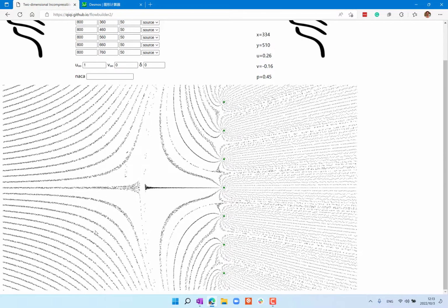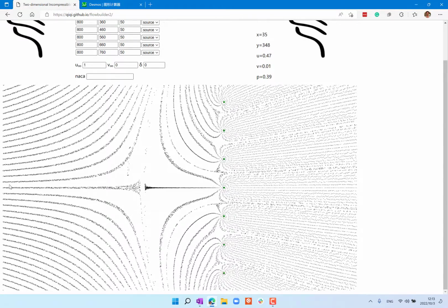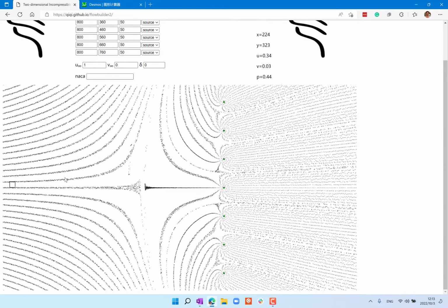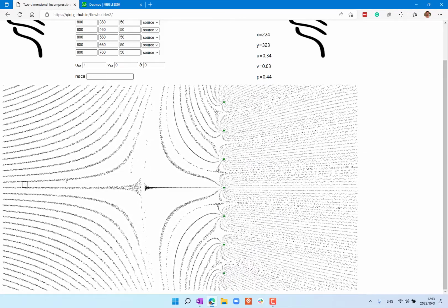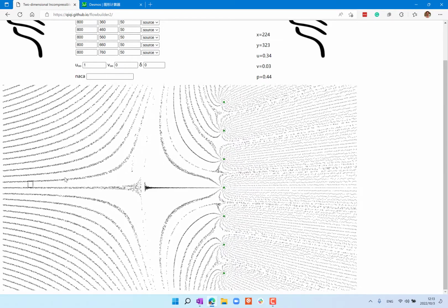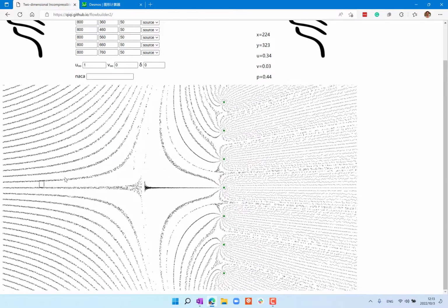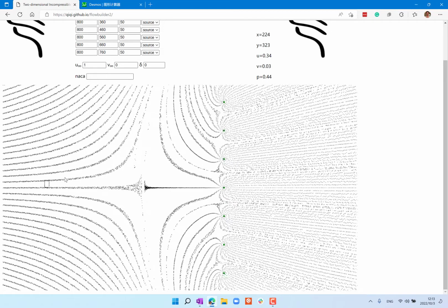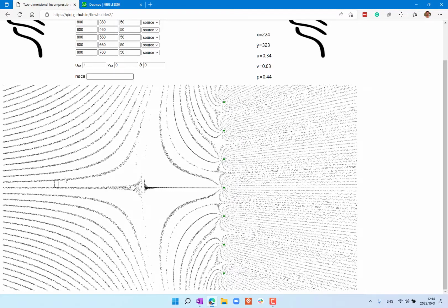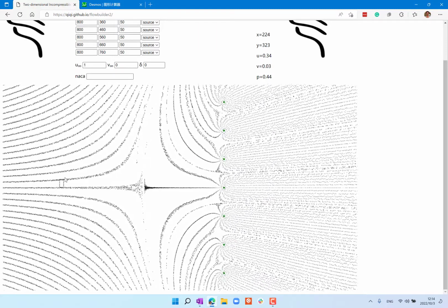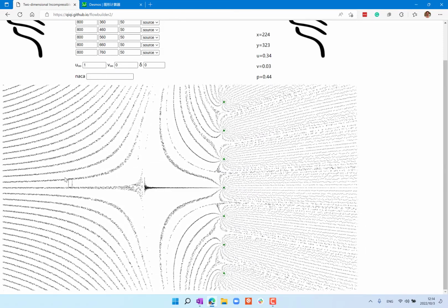Yes? Just explain one more time. Oh, why it's elongated? Let's imagine I see the square over here, right? The upper and lower bounds of the square are exactly the boundary of two streamlines. This streamline, as you go downstream, widens because the velocity decreases, right? So it has to be pulled apart on the top and lower parts. At the same time, we have conservation of mass, so in the x direction, it has to be squeezed. All right, make sense? Yep.